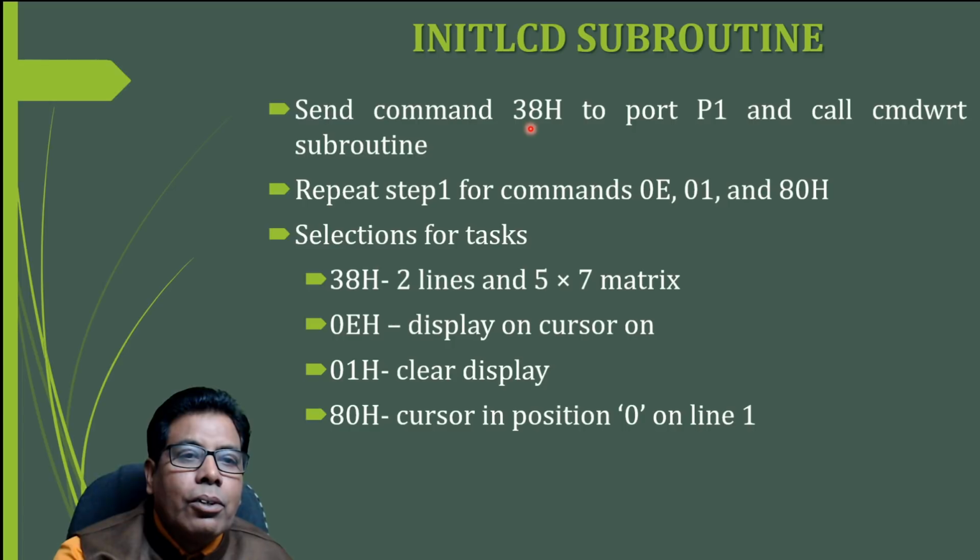So we have to first specify the display type. 38, we have seen, it is for the 2-line display, 5x7 matrix, 16x2, 5x7 matrix. And call the command write.